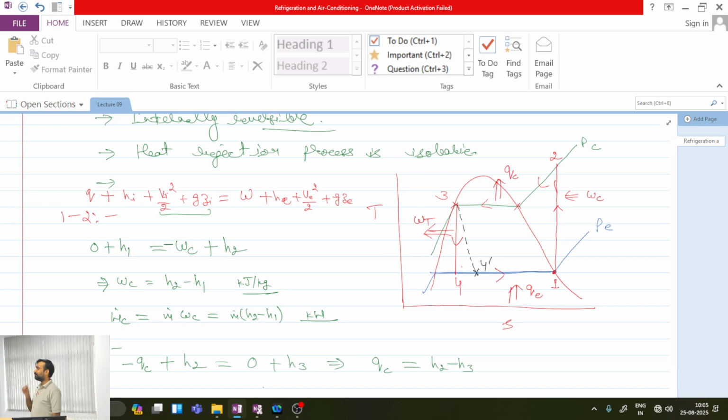There are multiple practical expansion devices available. For example, the oldest systems had a very small diameter, long capillary tube as the expansion device. Nowadays we have automatic, orifice size controlled expansion devices. There can also be a porous structure as an expansion device. When the fluid flows through the pores, ultimately it decreases in pressure. The process which takes place in the expansion device is the throttling process.